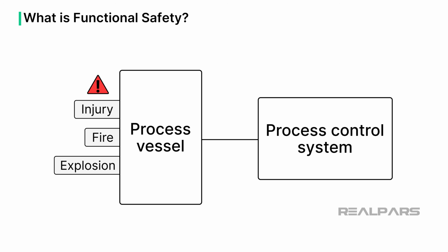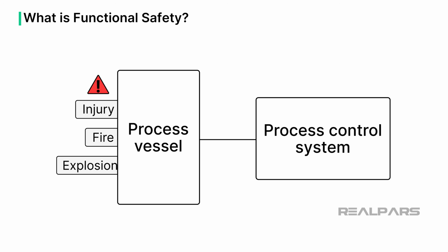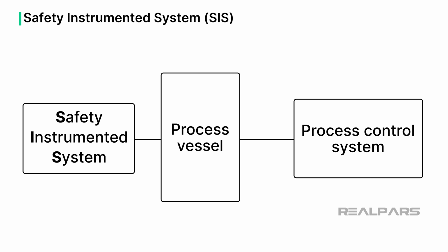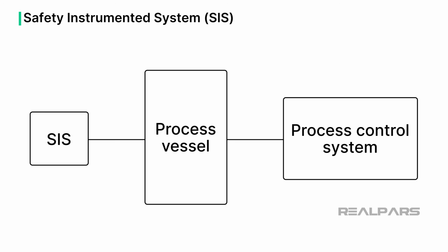Deploying a functional safety system allows for an automated, safe shutdown of processing units in instances of unusually risky or potentially catastrophic situations that exceed the capabilities of the automatic process control system or trained operators to rectify. Adding another layer of protection called the Safety Instrumented System, or SIS, moves us closer to achieving the desired functional safety condition. Okay, so let's be clear.